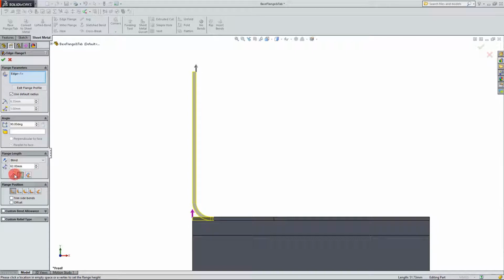So these are just different ways of dimensioning, but oftentimes I find it useful to just use the first feature, the same way that we did in the flange position, to use outer virtual sharp. To me at least, it's the most intuitive because you're measuring from the bottom of the edge.